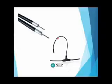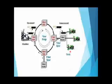A junction box containing amplifiers takes the signals and redistributes them to smaller cables called feeders. So these are the feeders, which go to specific areas and neighborhoods. From there the signals are again rejuvenated with amplifiers and sent to individual homes by coaxial cables called drops. The overall system is referred to as a hybrid fiber coax, or HFC, system. So this is an example of an HFC system.